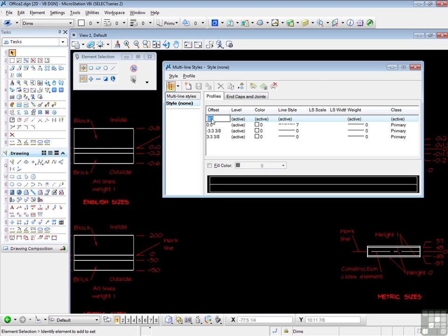So we will click on the offset value, change that to 8, and we'll tab down. So now we have the outside wall line set at an 8-inch offset from 0, 0. We need 0, 0 in place, so that line remains exactly as it is. The next one is the negative 2 and later the negative 6. Let's do the negative 2 next. So we activate that, and we can enter 0, 2, and we'll enter for that one. And this one will be negative 6.